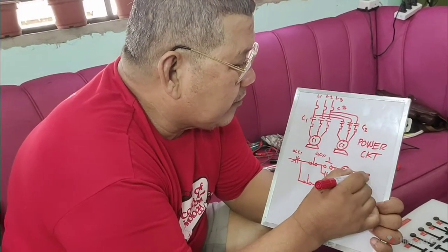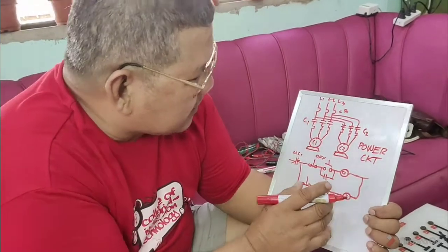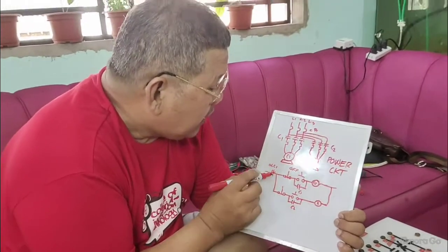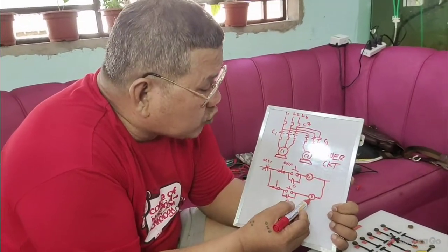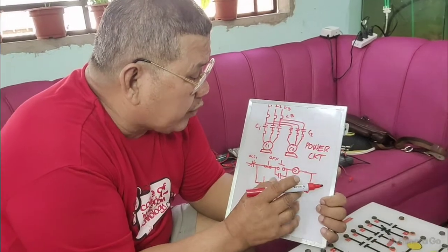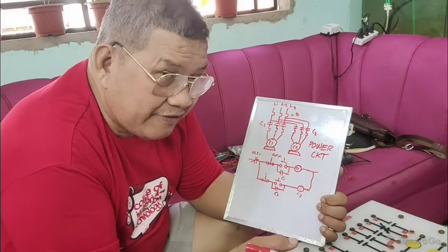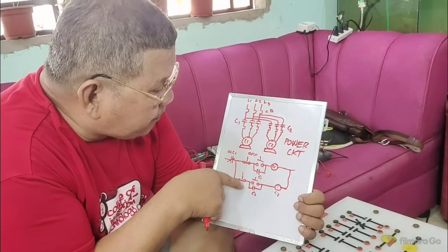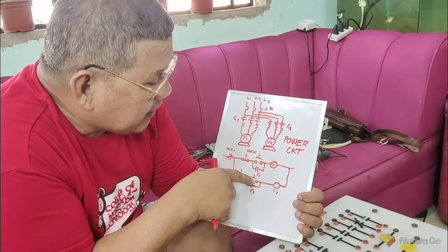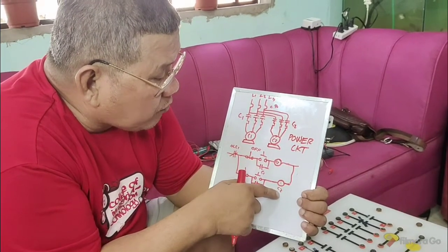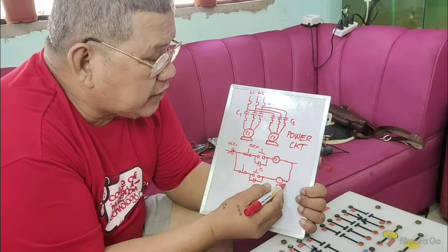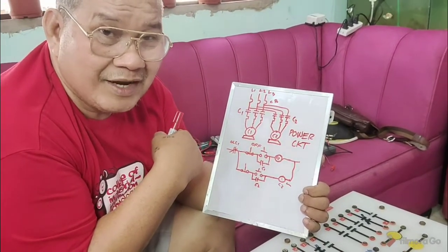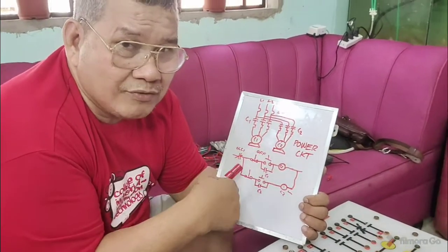Okay, look at this. Now this is not the correct diagram, but I will tell you first the difference. I said motor conveyor number 2 will only run when conveyor number 1 is energized, right? But this time, if I immediately press push button 2 intended for conveyor number 2, what will happen? Immediately the motor will run, even without running conveyor number 1. Right? So how would you meet the condition?